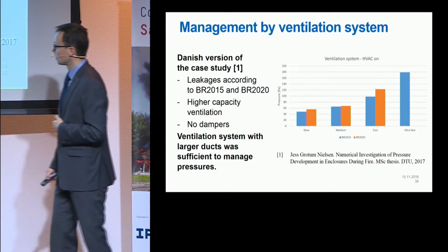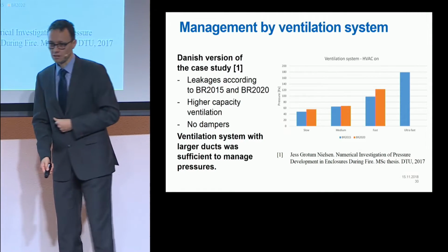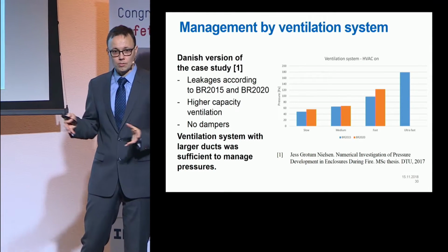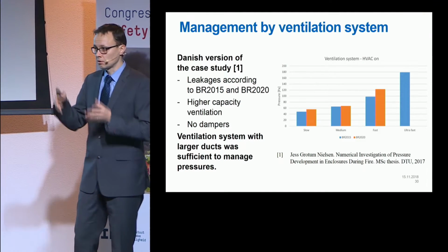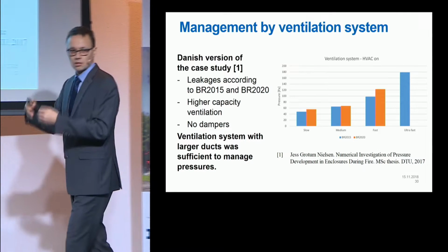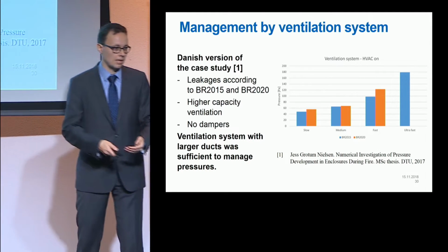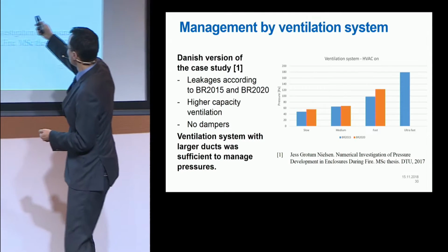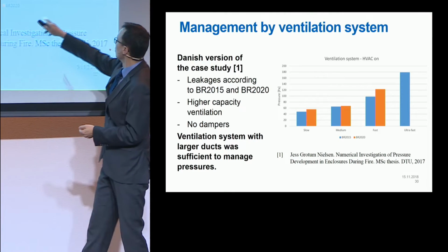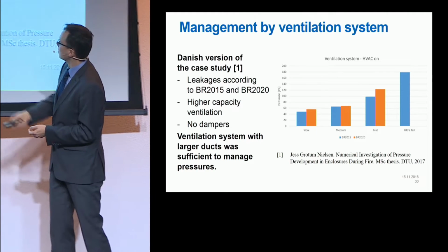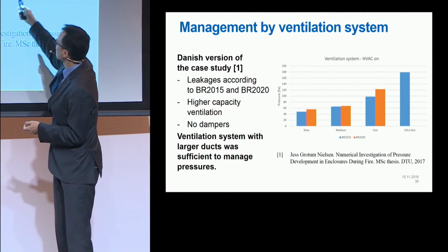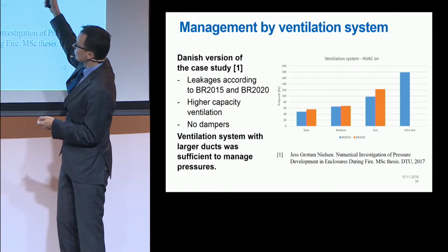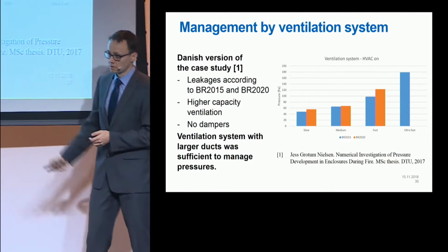On the other hand, Jes Grotum Nielsen from DTU made his master thesis where he took our modeling scenario and modified it to comply with the Danish ventilation design standard. What he saw was that with different fires from slow to ultra fast, in most cases the pressures were quite close to 100 Pascal.